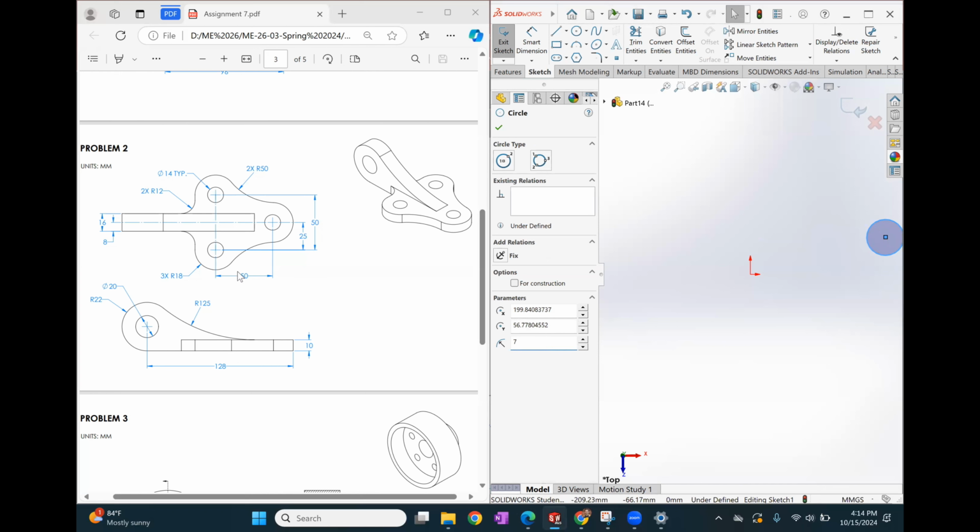This one, I will position it. I want this axis to go down the middle. So this first circle, I'll make it 50 units in the X direction, and then, I'm sorry, this is going to be 0 in the Y. So we want 50 units in the X direction, 0 in the Y. That way this X axis splits our drawing.